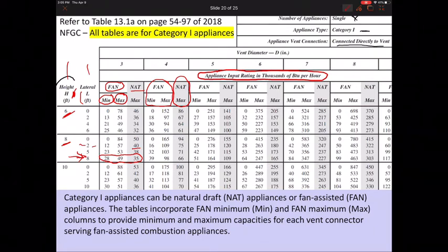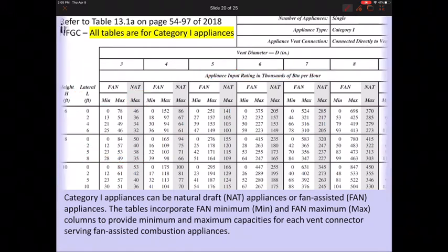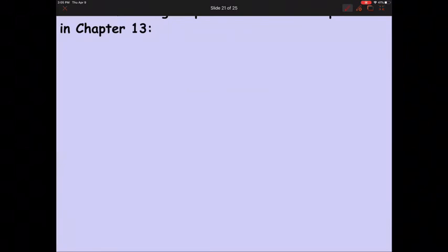So that means if I had a third elbow on a system, that 35,000, if I had to take off 10% of that, if that's the penalty, then I'm going to specifically hit on this one: 10% of 35,000 is 3,500. I'd have to subtract 3,500 BTUs off of 35,000. So the capacity now would be only 31,500 in that example. You have to kind of watch those numbers, and there's a little bit of figuring to do.